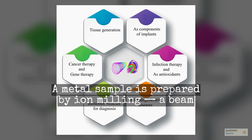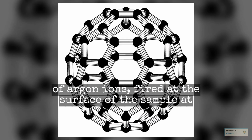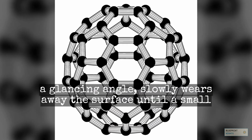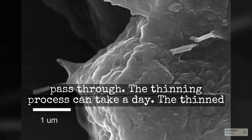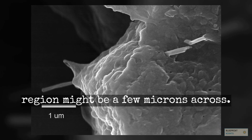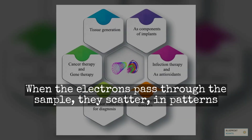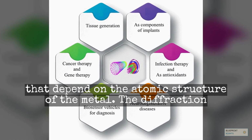A metal sample is prepared by ion milling. A beam of argon ions, fired at the surface of the sample at a glancing angle, slowly wears away the surface until a small region in the center is thin enough for the electrons to pass through. When the electrons pass through the sample, they scatter in patterns that depend on the atomic structure of the metal.